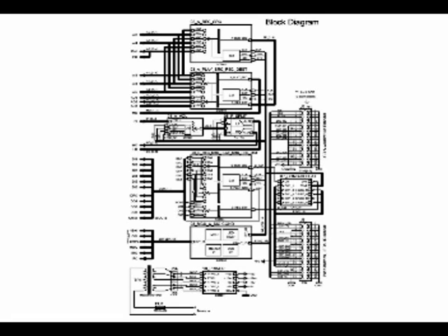The topmost two blocks select an analog source to send to a recorder or amplifier. The output from the JVC's preamplifier goes to the external 4BX and graphic equalizer units, then returns to a Switchbox input, which goes to the 4-channel volume control and thence to a frequency splitter. The splitter divides the audio into low and high bands for sending to the treble Onkyo amplifier and bass JVC amplifier. Another block handles the digital signals, which require only one wire each, even for DTS surround.